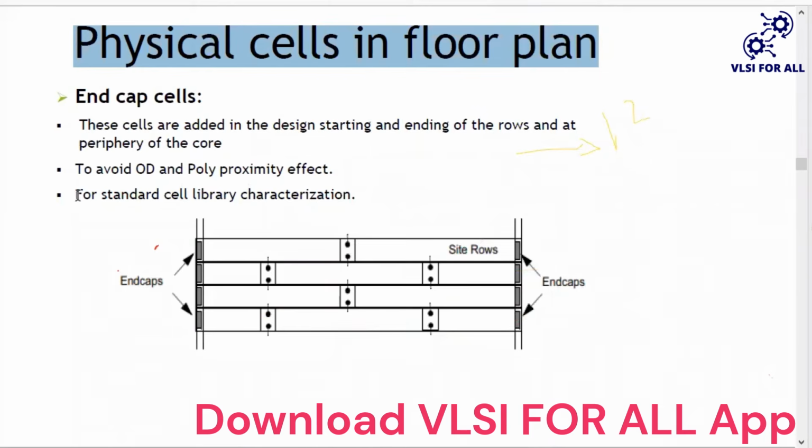Okay, this is the standard cell. Next one is the standard cell site rows, which are easy to find in every design. In the standard cell site rows, combinational cells and sequential cells will be placed. But sometimes there are also double heighted cells in the design. Double heighted cells can also be considered standard cells, but there will be a separate library, a separate tech LEF.